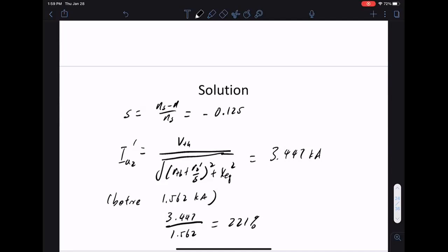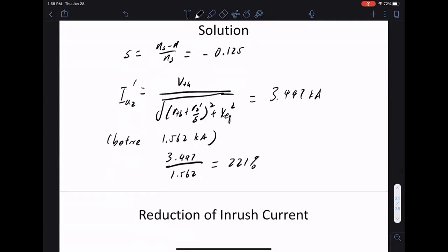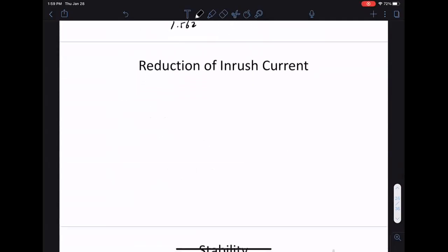So we're mostly worried about short circuit faults, and short circuit faults lead to large current. That's why a lot of protection is set to trip after this kind of behavior, right? Other faults do happen, but many faults that reduce the voltage, for example, are very local. So this sort of short circuit tends to produce large current, and that's why we protect against it. Okay? So if a turbine looks like a short circuit fault, that's obviously not ideal. It's asking a lot of protection devices to figure out what's actually going on. So there are ways to reduce this inrush current.